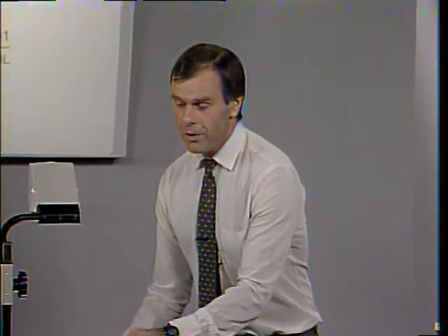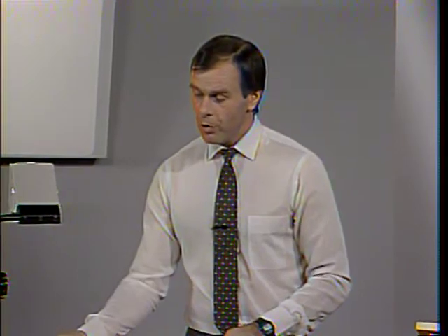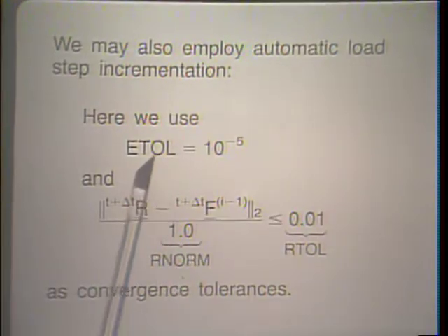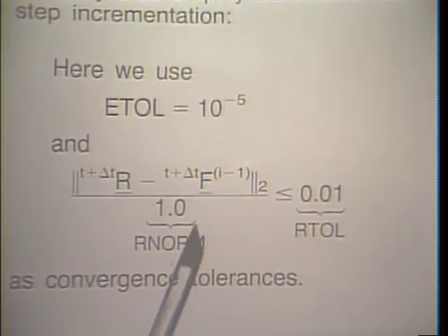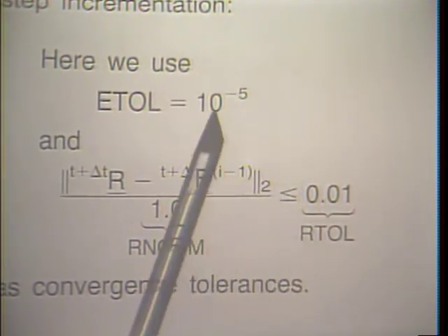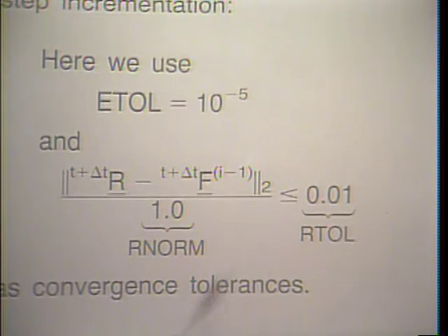We, of course, may also perform the analysis using the automatic load stepping algorithm. Here we use this tolerance, etol, and rtol this tolerance. R norm is shown here. These are once again default tolerances in the ADINA program.